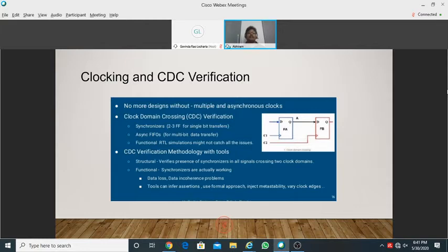And also there are a lot of async FIFOs for bigger data bus designs. Now you have a big bus like 128-bit or 256-bit, or you can take 1024-bit. So those big bus widths are moving from one domain to another domain. So you see that the domain crossings are perfect. So all these we need to do a detailed CDC verification as well to reduce the data loss and metastability related issues. Okay, so that is where this verification covers.